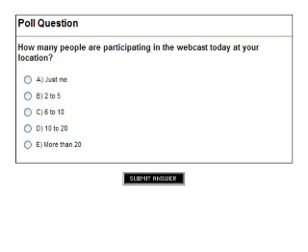Another question is, how would you add disinfection to an existing CSO facility on a small footprint that does not have disinfection and virtually no room for chlorination, dechlorination, perhaps due to industrial wastes? Because due to industrial waste, UV would not be effective. Well, in Columbus, it's a good example. It's the satellite facility. There's very little room in that facility.